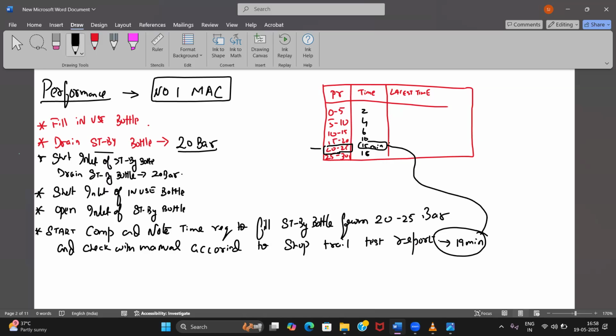Yes sir. The performance drop reasons that I showed, that could be there, right? Leakages and all those things. Your suction valves leaking, your piston rings leaking, filter is choked, right? Intercooler is not giving efficient cooling, air leakages. Okay, so the clearance volume is increasing. So all these points can come, right? But do you understand how to test the performance of a compressor? Yes, sir. Chalo.